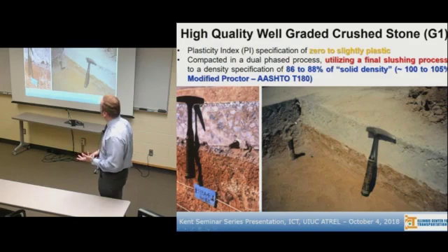How they build that base and how they test it with the head of a hammer, they call this the ping test. You should hear a ping as if from concrete. This is the way they tested whether it was properly done as a high quality crushed base. This is amazing. It surely looks like concrete, and there's a reason why it does.